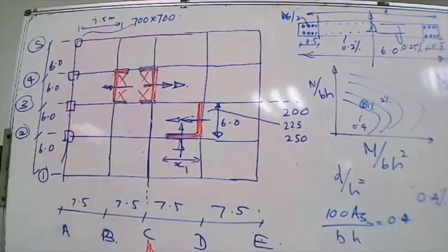So basically, you have to look at the lecture: less than 5 stories, no shear wall, one method. Up to 10 floors, another method, but again you use a simple model, like a 2D model, converting everything to a 2D model. Whereas when I'm going for a 20-story or more, now it's time to be a little more accurate.